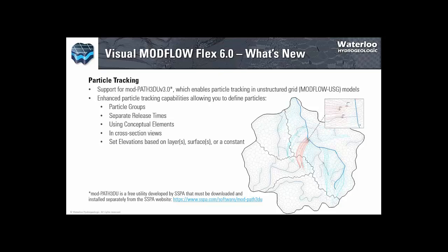We've also added some significant capabilities around how you define particles. So you can now define individual groups of particles, each with their own separate release time. You can also have various groups defined based on conceptual elements, and we'll do that in the demo. You can also define particles in the cross-section view of the finite difference grids, and then also set elevations based on conceptual elements such as layers, surfaces, or even a constant value.